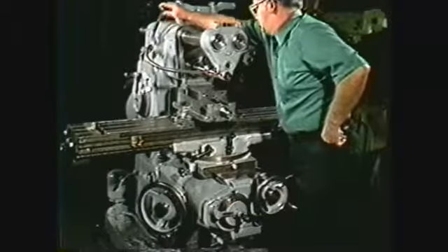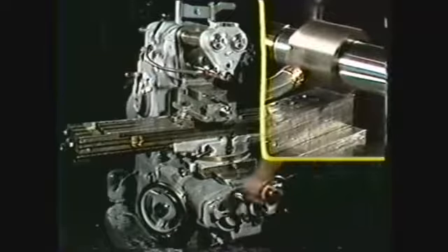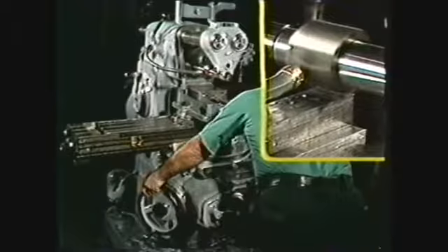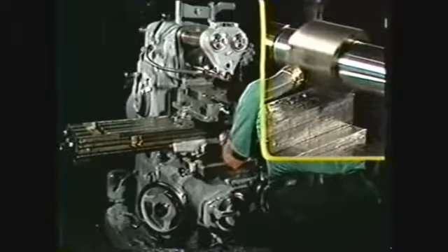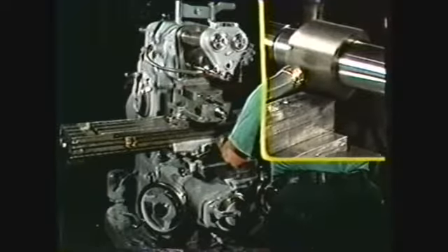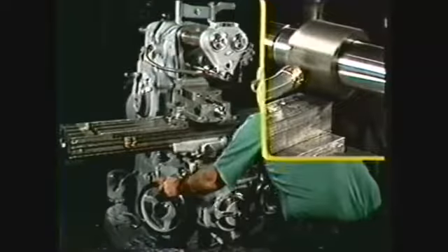Turn on the machine to start the spindle and notice the direction of rotation of the cutter. Using the vertical table feed, bring the work up slowly to make contact with the cutter. Move the work away from under the cutter and position the table so that the work will be fed into the cutter for conventional or up milling.